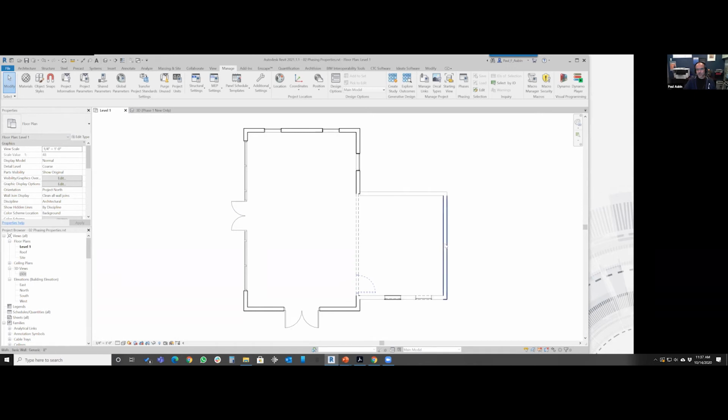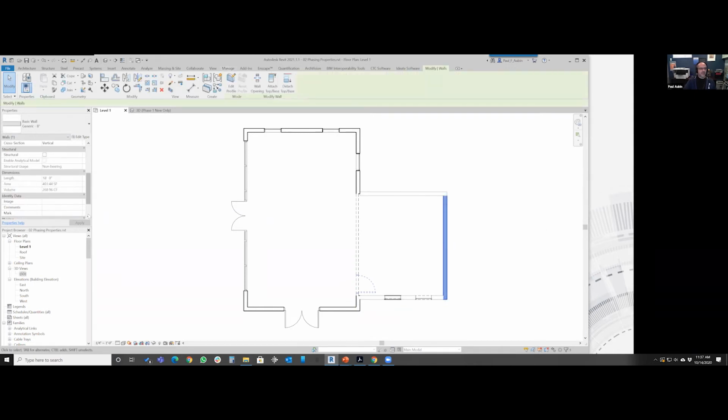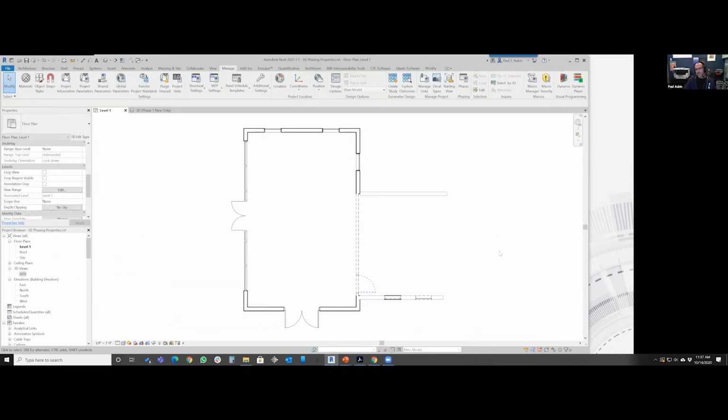So now at this point, I could change these objects and those new phases would appear on the list. So for example, if I set that wall to new phase 2, it disappears. Why? It's Marty's house, right? And we're back in 1955 and his house doesn't exist until much later. So that's what just happened with that wall. It's disappeared. Now, with nothing selected, we can then consider the phases of the view itself.